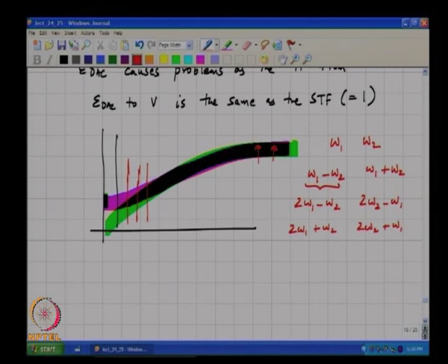This quantization noise will also fold back into the signal band due to these nonlinearities. Does it make sense? And therefore, what has happened now? All the hard work that you put in to try and shape the noise out of the signal band has been brought to naught simply because of errors in the output levels of the D to A converter. Does it make sense?